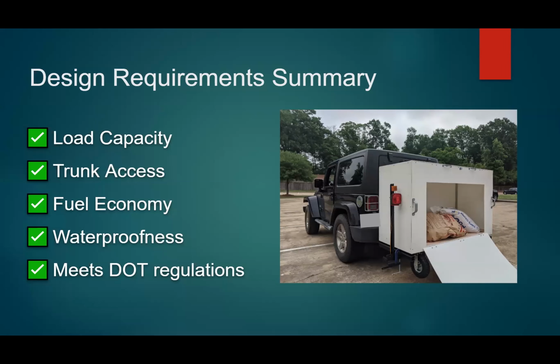Of course. In the simulation, what we were trying to simulate was just really big bumps in the road. So we assumed a max force of a little bit more than what we anticipate. The enclosure itself is around 65 pounds, and plus the 150, we went a little bit more than that, at about 250 pounds. So we had an alternating force between 0, simulating free fall, and then the 250 pounds. Okay, thank you.